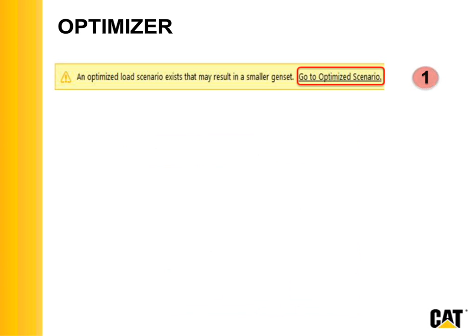So what we did when we developed the online web tool, we developed logic so that the optimizer or the Wizard runs in the background all the time, every time. So when you click the Select Genset page link, it kicks off that optimizer. And so, you'll size a genset based upon your load scenario, based upon the loads as you sequence them.